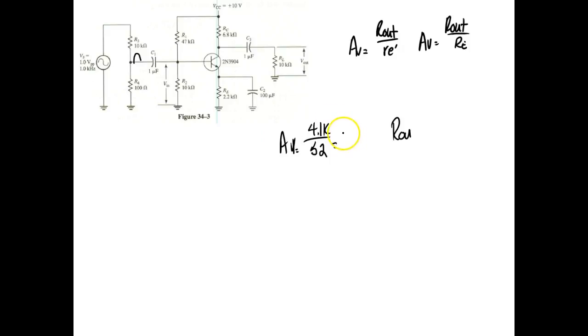And of course, we calculated 78. So here, AC has got to flow through that resistor right there. Before, my AC signal was bypassing that resistor. Now it's got to go through that resistor. So now my gain is going to be equal to 1.4K over 2.2K. So my gain is going to drop down drastically, right?